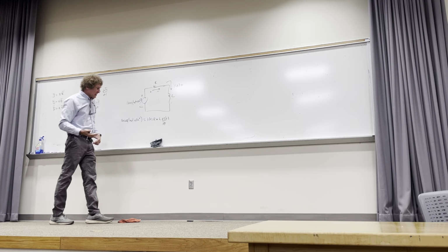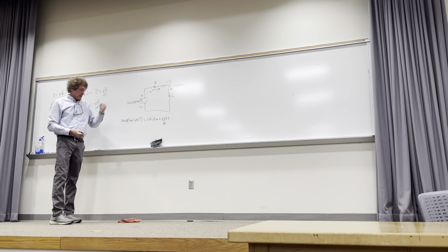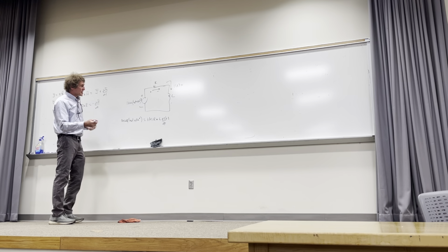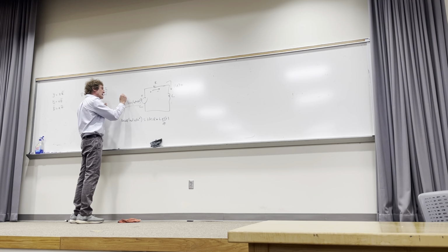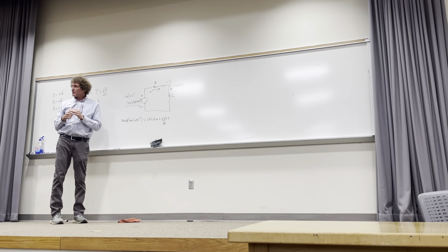Now you realize that's the differential equation that describes that. If you're a physicist or a mathematician, you might try to solve that problem this way. But we're electrical engineers. We don't do that. What we do is take this voltage and make it 10 at an angle of 30 degrees. Y'all remember this? This is a phasor.